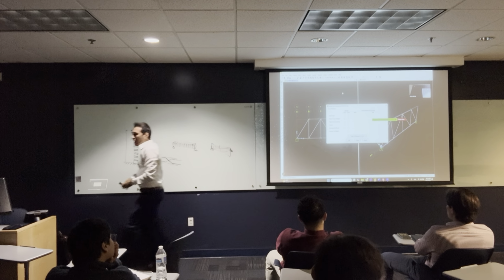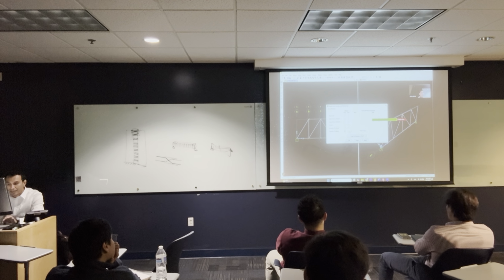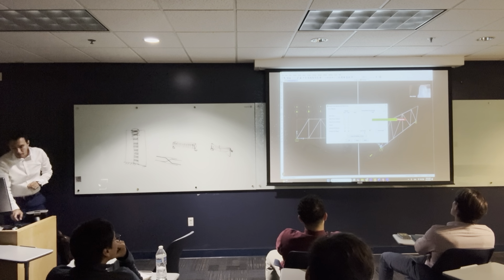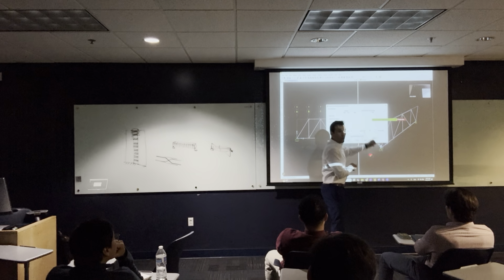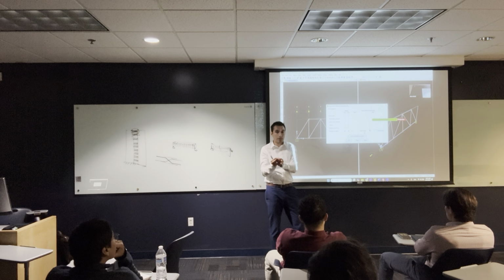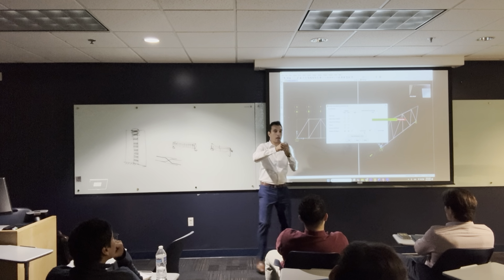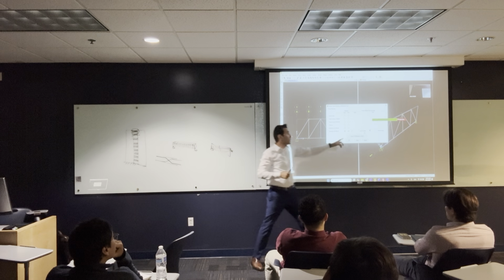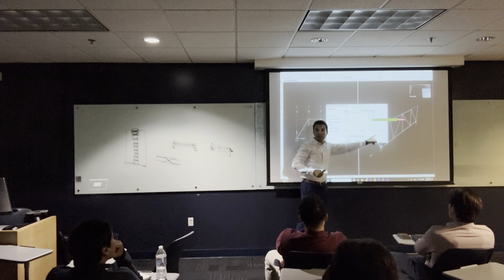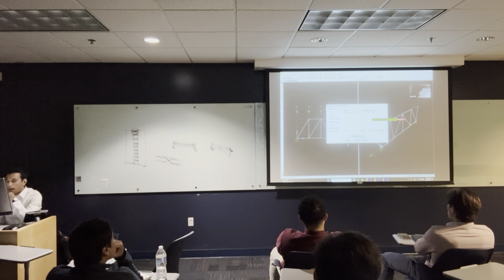So let's say that the resistance of each joint to the moment M3 at the start is equal to 0, at the end equal to 0. And look at the unit of the value here: it is ton-force meter per radian, which is the unit of a rotational spring stiffness. So basically, if you want to solve structures that have springs, you have to put the spring stiffness here at the start and the end. Okay? All right. So let's put this, and I'm gonna hit OK.